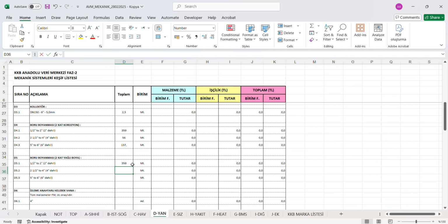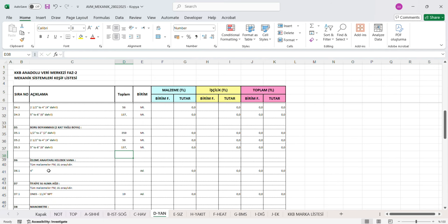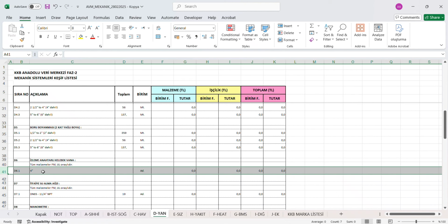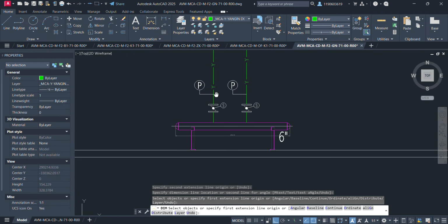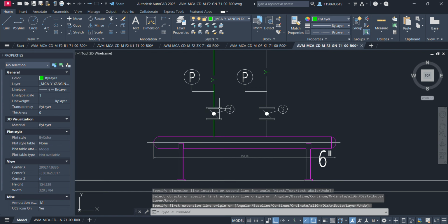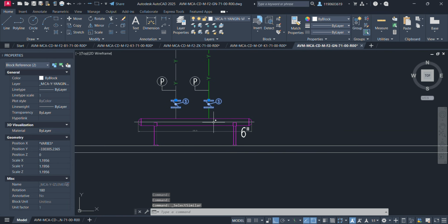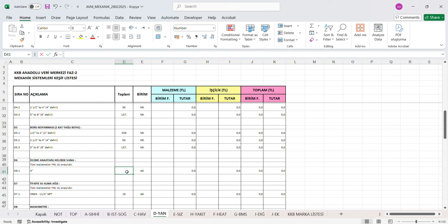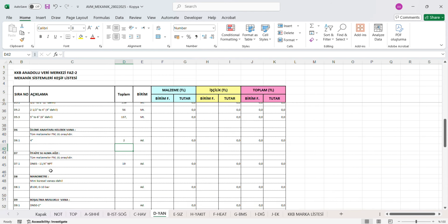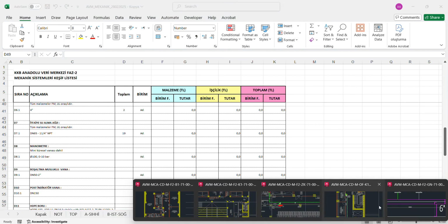How to calculate the required tank size. Calculating the size of the fire tank depends on several factors, including the number of sprinklers and outlets to be used, the required water pressure for effective system operation, the size of the area or building and the type of activity, e.g. industrial or residential. Based on accurate engineering calculations, the required tank size can be determined. The tank must be capable of providing sufficient water for the system to operate efficiently.